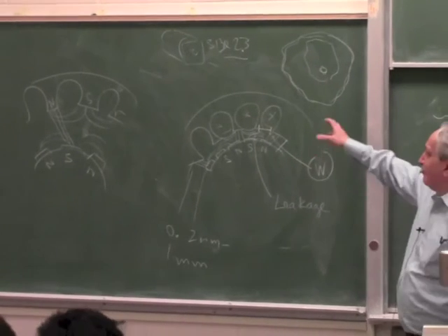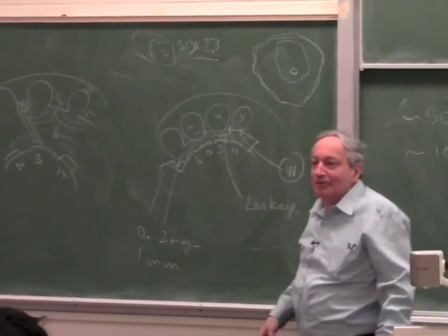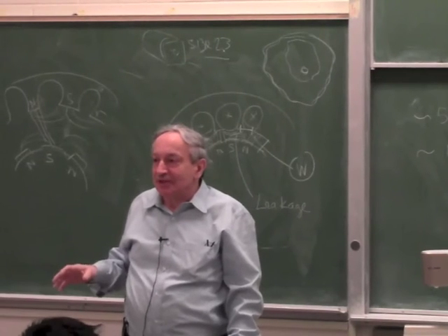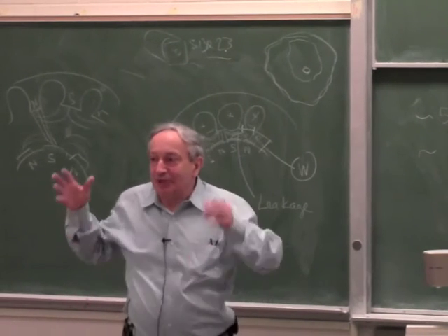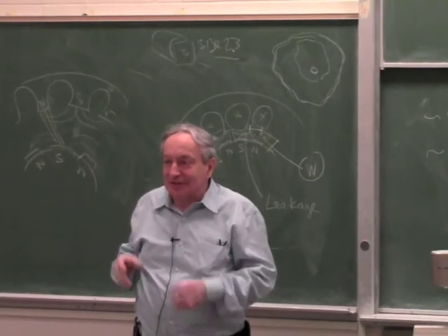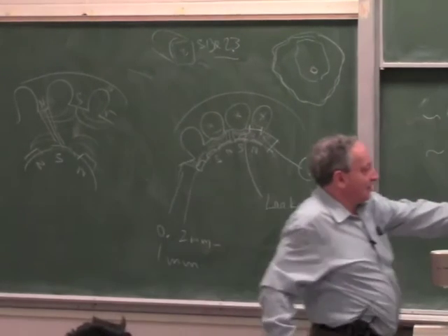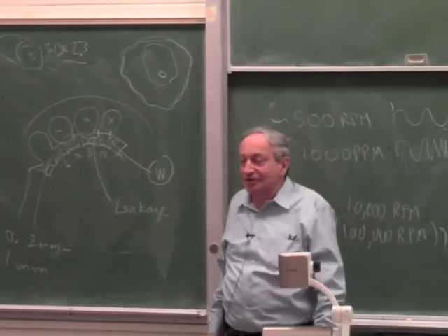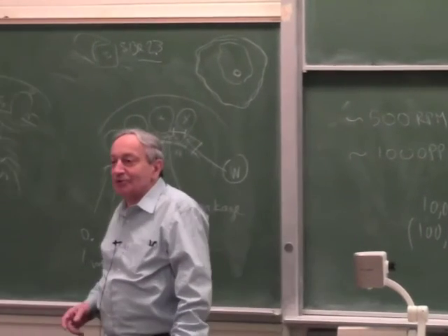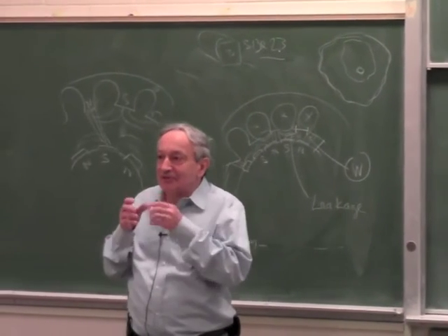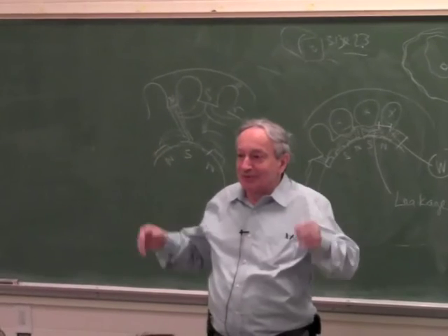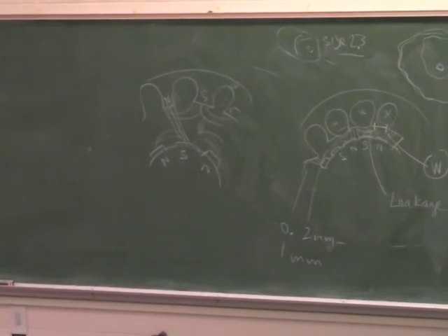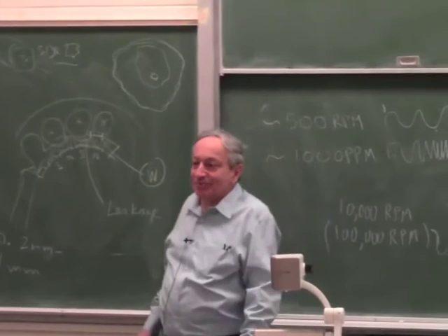I mean, these are all kind of fine details. I'm not sure you need to remember all that, but if you look, say, at a CNC machine tool, a CNC machine tool doesn't have big steppers to move. It has little motors like that, little 2-pole motors. It still has synchronous motors. Most machine tools still use synchronous motors, but little motors with gearing instead of big motors with many poles. And the reason is that's cheaper. For the same performance, you can make this go much faster, and it's cheaper.